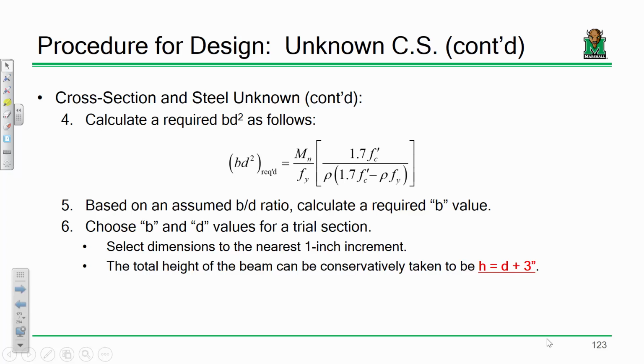For now, just know that they are there. Later on, we will design those bars. The short answer is these bars here, these ones, are helping to resist moment. But these, which we call stirrups, are put there to resist shear. So you have a beam that has a shear diagram and a moment diagram. These things are improving the concrete beam's shear capacity.